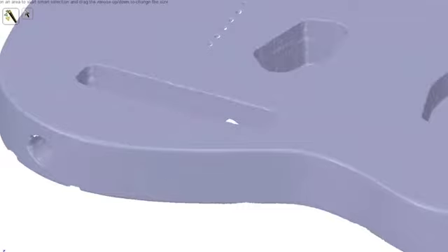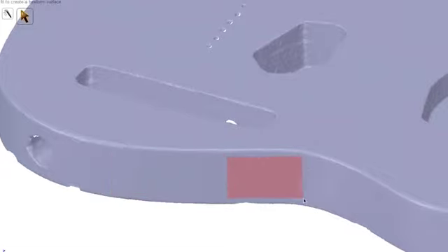If I just create a manual selection on this area, you can see this is an organic shape here on screen. I'll hold Shift and make sure I select enough geometry. This will be a basic example. If I come over to Freeform and I tell it to fit, it'll look at that geometry and fit a freeform square patch to the geometry that's there. It'll take it a second before it shows up on screen.